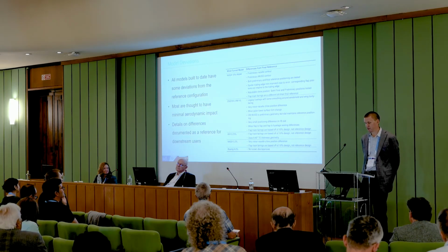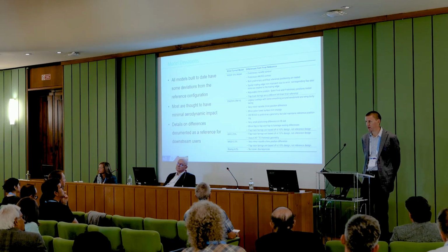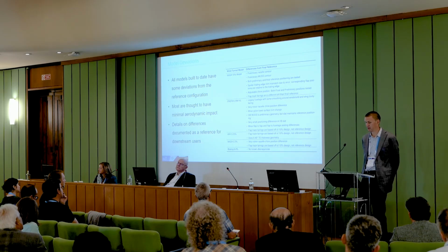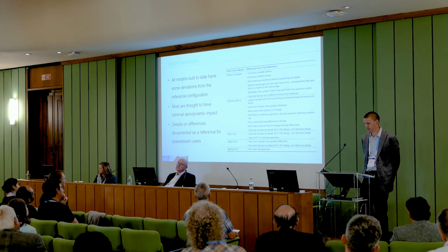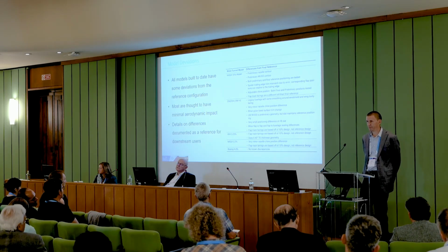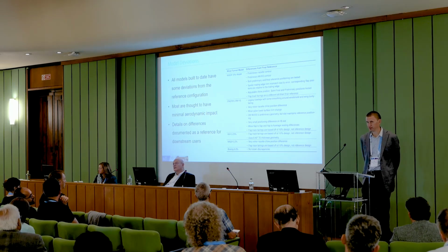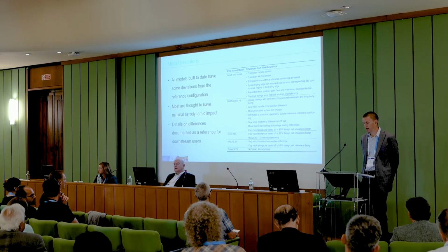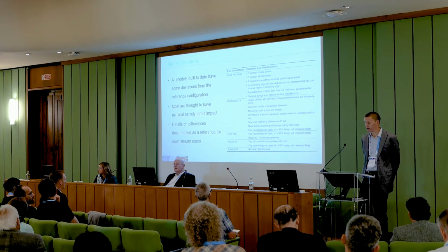Then the next model that was built was the Onera. They're calling it the LRM, the large reference model. That one has a few differences that are worth highlighting. They have a fuselage definition that carries back to the transonic CRM days. They smoothed the nose of that a little bit. Very minor position differences in a couple of the surfaces, like the chine, the trim surface on the bottom of the pylon. The outboard wing under slat surface is preliminary geometry, just because of when that surface was available. But the slats are maintaining the correct reference positions.